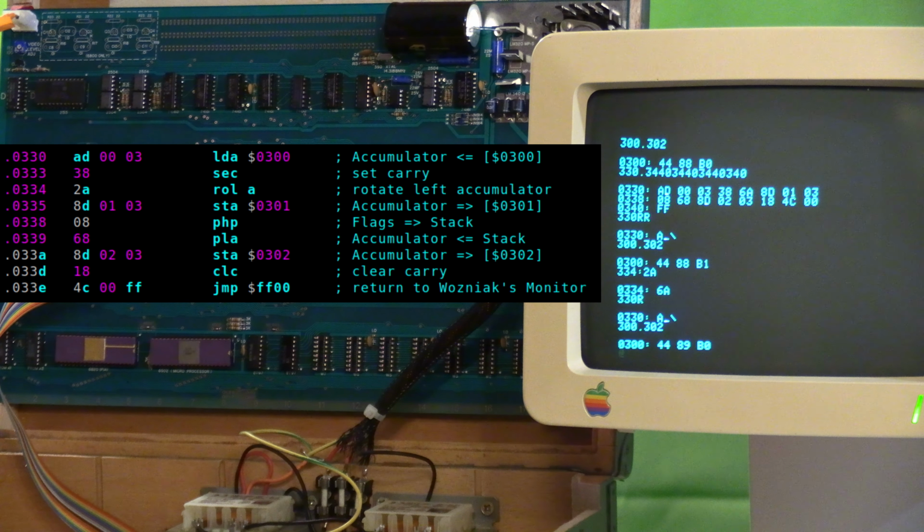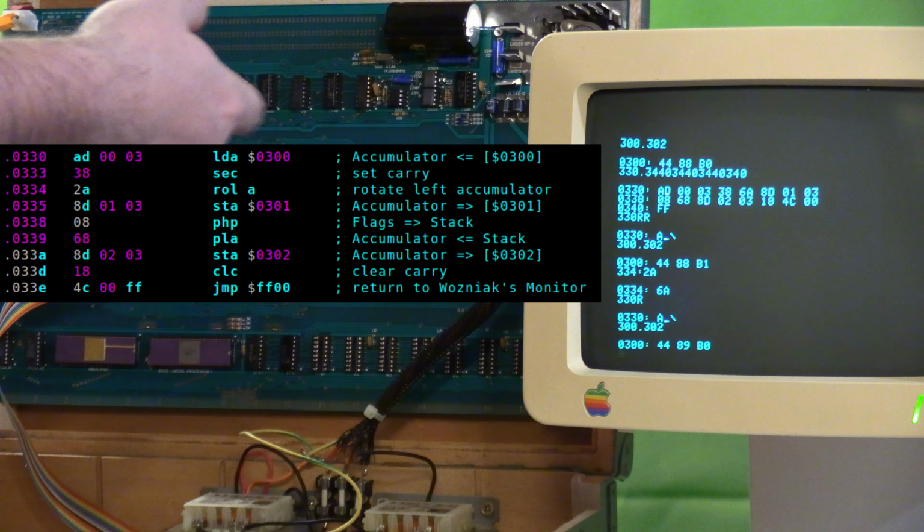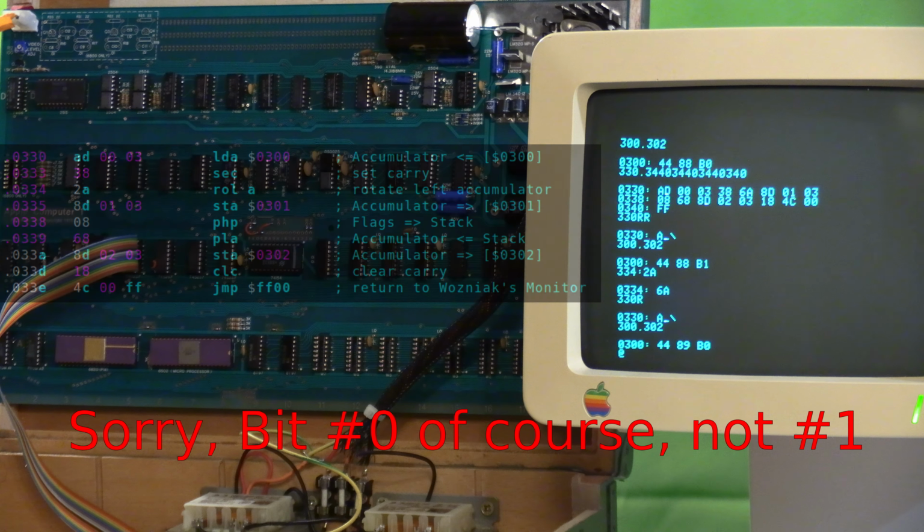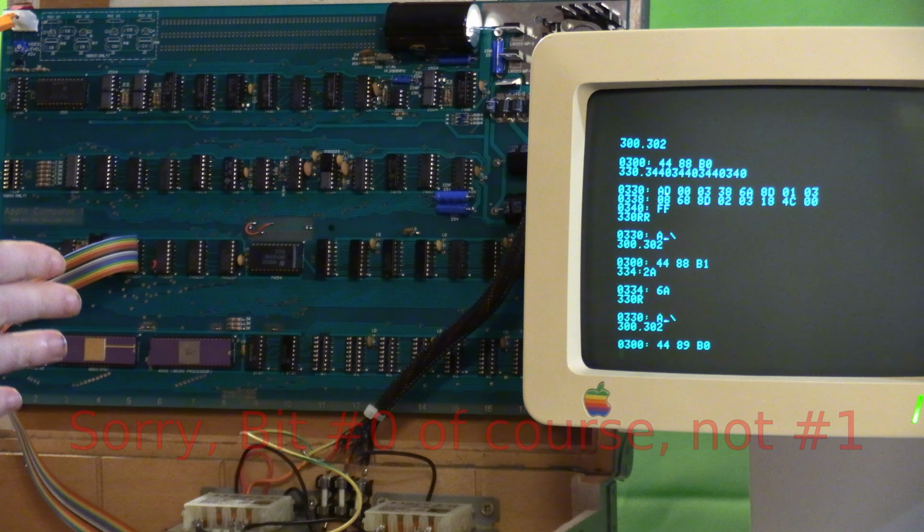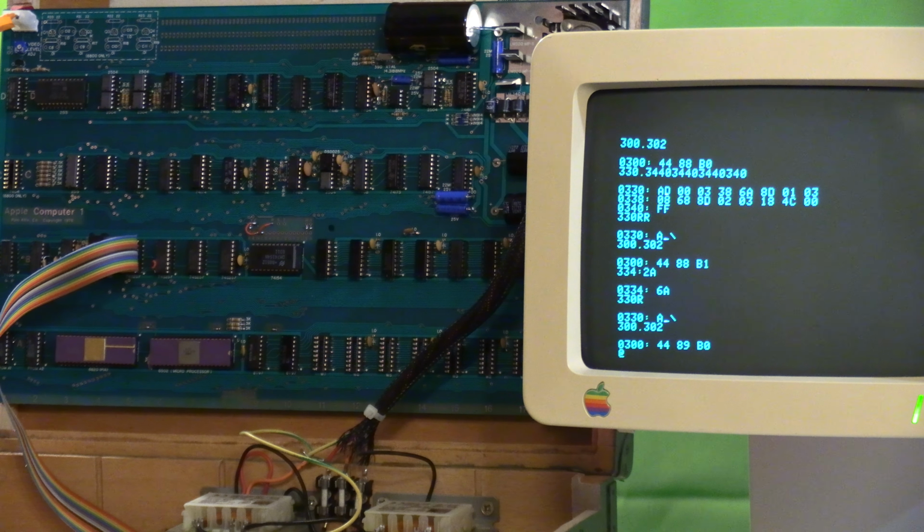This is expected as the roll instruction should really shift in the carry from the right correctly. So bit number 1 gets set. This is the proof that in this faulty CPU the ROR instruction behaves like arithmetic shift left.